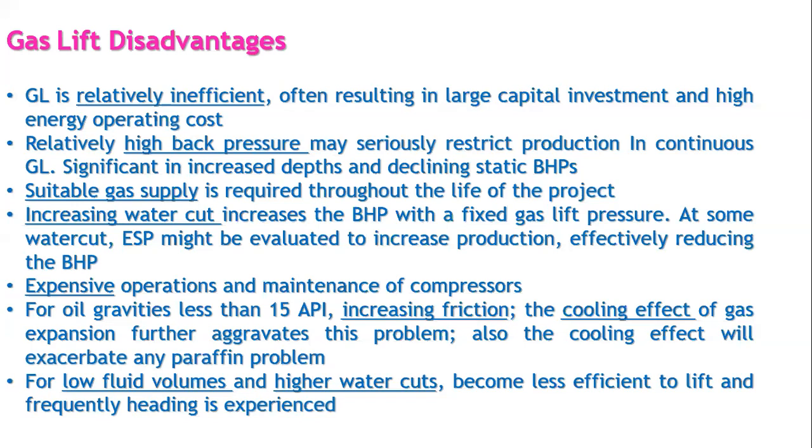Another point is that the gas lift supply should last for the life of the project. Increasing water cut also increases the borehole pressure with a fixed gas lift pressure, which is the design we originally made. With some water cut, another type of artificial lift, like an ESP, which handles a lot of high volume, should be considered.